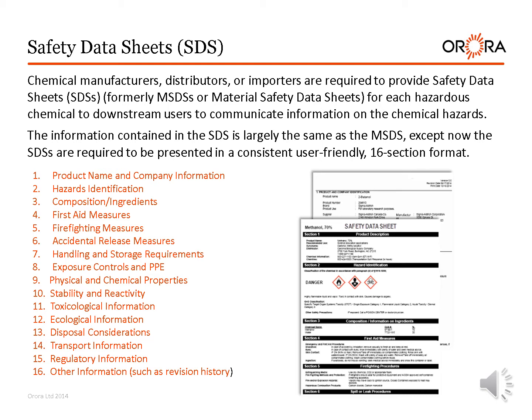Section 1, Identification, includes all chemical product identifiers, supplier, manufacturer or distributor name and detailed contact information, recommended use, and restrictions on use, and emergency contact phone number. Section 2, Hazard Identification, includes exact classification of the chemical substance, all hazards, and required GHS label elements including precautionary statements and pictograms. Section 3, Composition/information on ingredients, includes all information on chemical ingredients and information on complex substances.